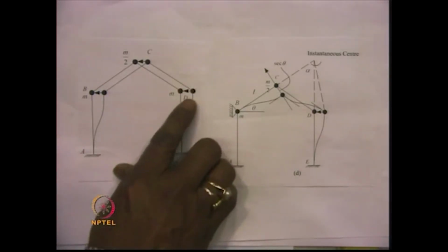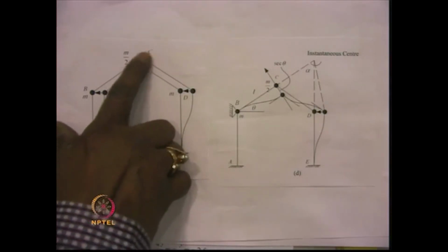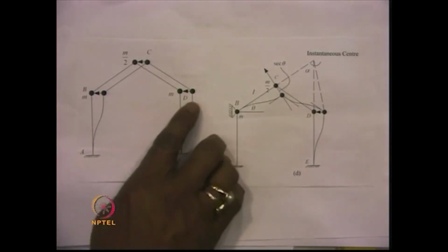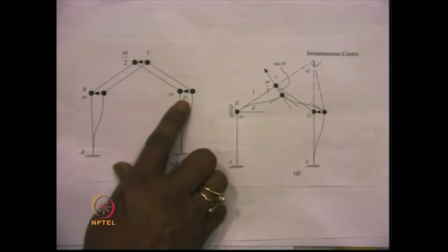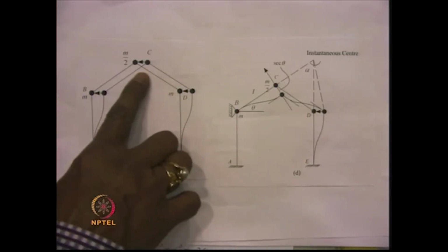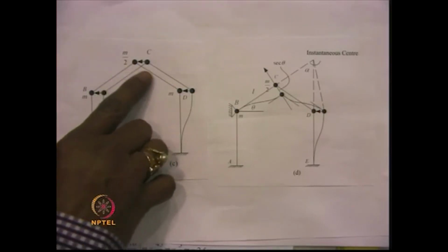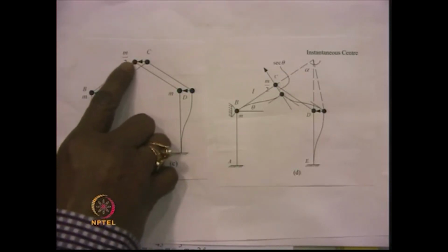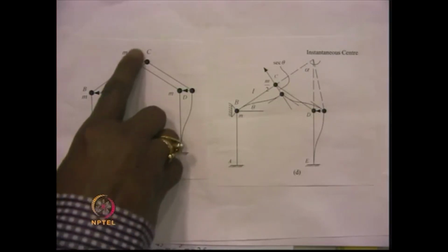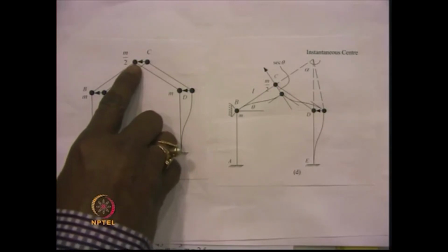Here also the inertia force will be equal to mass times the unit acceleration, and at this point also we will have an inertia force which will be m by 2 multiplied by the unit acceleration acting in the horizontal direction. Since we do not have any degree of freedom declared at this point, this force is decomposed, one in this direction, other in the direction along this member, and this force is finally transferred to this point. At this point now we have got two forces, one force along this, the other force in the horizontal direction. We take the component of these two forces, one in the vertical direction, that is the direction of the chosen translation degree of freedom, and the other along this member.